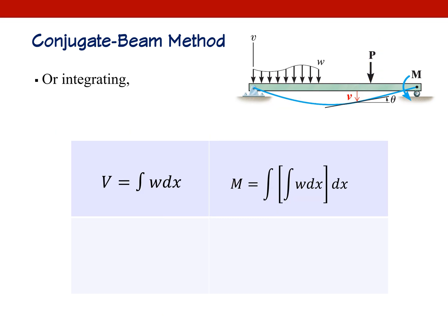If you use integration, the shear force and bending moment diagrams have this relationship. If you integrate your load, then you are going to get shear force. This is your shear force. So if you integrate shear force, then you are going to get bending moment.